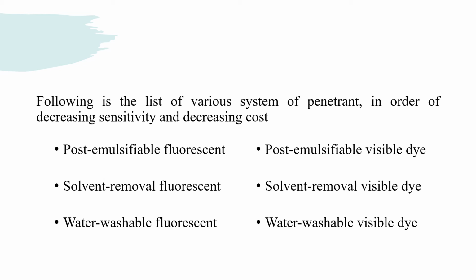From here it is found that visible dye penetrant can detect cracks having a width of approximately 5 micrometer, whereas fluorescent penetrant can detect cracks having a width range of 1 to 2 micrometer.